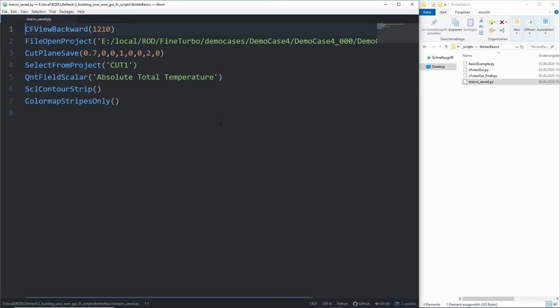Alright, everything we did can be reduced to 7 commands. The very first command is a very important one. That's the way you can access our API. Once you copy that command to the beginning of your Python file where you wrote your GUI, you're going to be able to call that GUI from CFView, and also use all the commands CFView understands. And here, as I said, it's very self-explanatory.